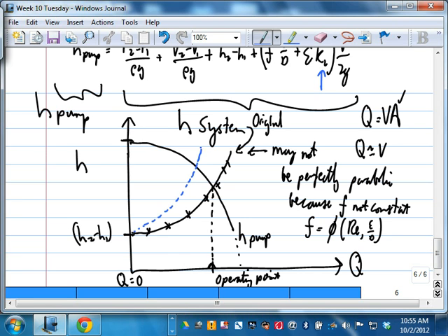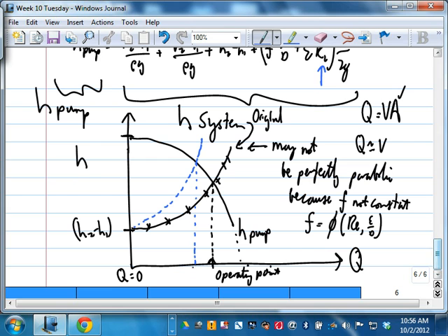Once the system reaches equilibrium after you put your itchy hands on the valve, the new flow rate will be lower, obviously. And that's all here. So that is Q goes down because K_L goes up.